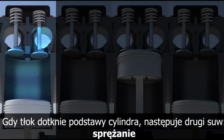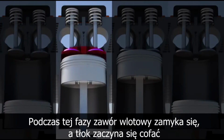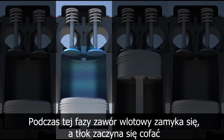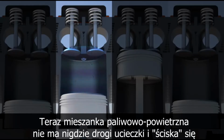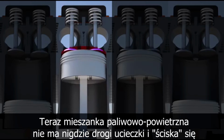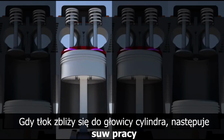Once the piston has reached the base of the cylinder, it's time for the second stroke, compression. During this phase, the intake valve is closed, and the piston reverses direction, moving back towards the cylinder head. This compresses the fuel-air mixture since it has nowhere to escape. Once the piston approaches the top of the cylinder, we begin the third stroke, power.